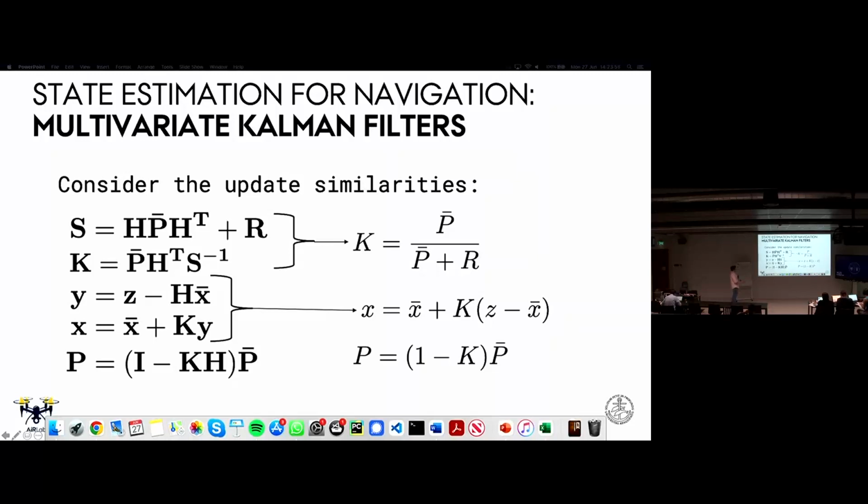If you have a univariate Kalman gain, the innovation covariance can be used to calculate the Kalman gain. The problem is that there are a number of different operations that you need to take on matrices. The bigger the matrices, the harder it is to invert in good time, so when you're designing your Kalman filter, you might need to keep that in mind.